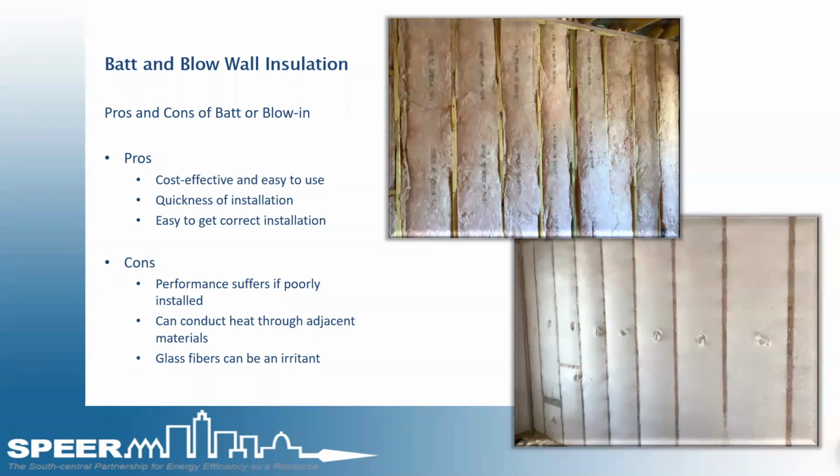It's harder to do when it's blown in, but the pros of both of these: basically cost effective, easy to use, quick of installation, easy to get corrected if you're going to do some corrections for that. The con basically is it performs poorly if it's not installed correctly. It can also conduct heat through adjacent materials, and fiberglass fibers can be an irritant.